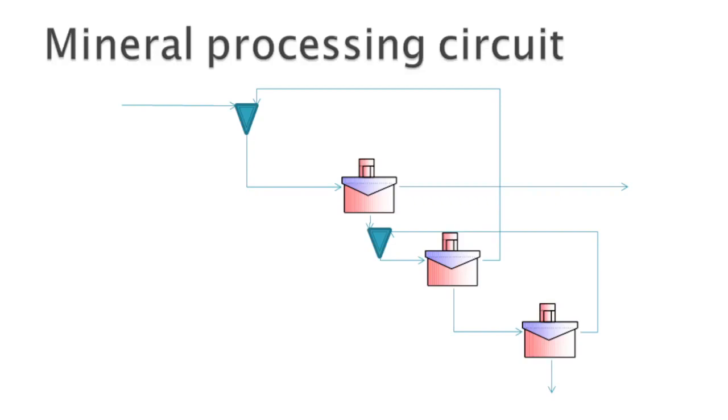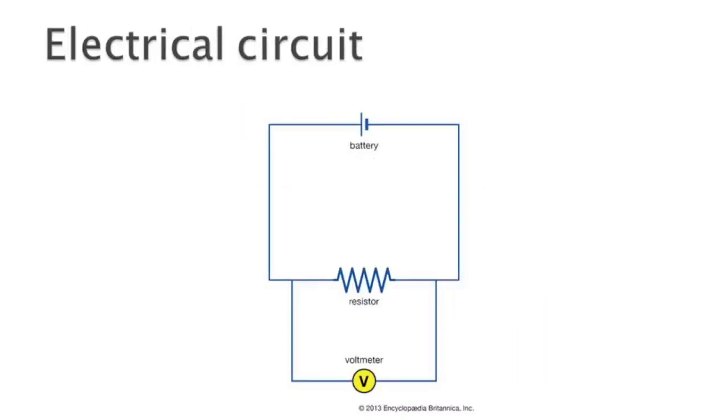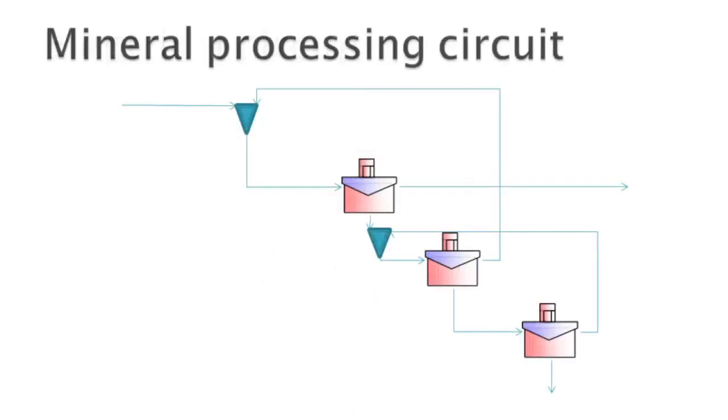So here we see the mineral processing circuit that I'm aiming to simulate. These are cleaners, and if you looked at video 3, which was model fitting, it gave us the flotation rates at each of these units. So they're inputted into the simulation system, and it has various recycles, and we have a con and we have a tail. Now, just to give you a slight digression, I could have inputted into it an electrical system as well. Now, it's important to understand that these type of flowcharts can be constructed in Excel. Now, this particular unit is not a cyclone.